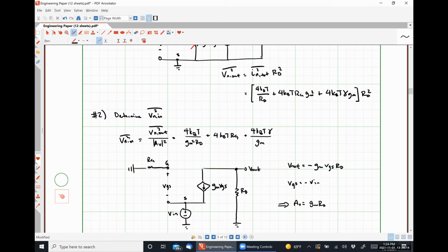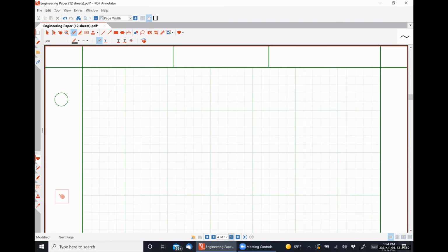When we find the input referred noise current, we're actually doing the exact same thing, except that we're no longer using a voltage gain, we're using, I guess it would be trans resistance gain, because we're converting an input current signal, that noise that's generated at the input, into an output noise voltage, right? So with that conceptually in mind,